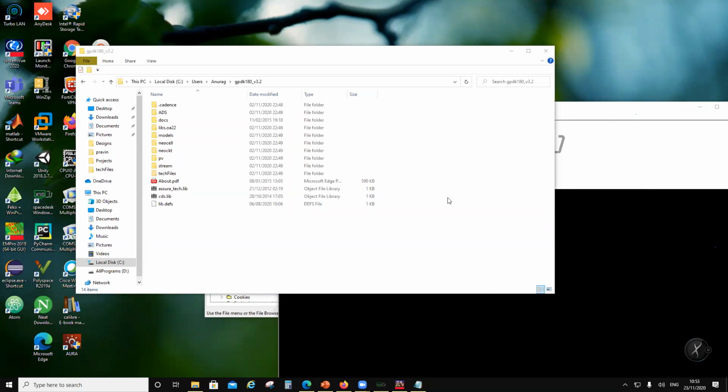I heard your question and I understood it. Let me explain what's happening. Circuit simulators versus EM simulators. Now we can do co-simulation. Co-simulation means that all the passives can be simulated in EM simulation, and those results can be brought into the circuit simulator, and then the whole thing can be simulated.